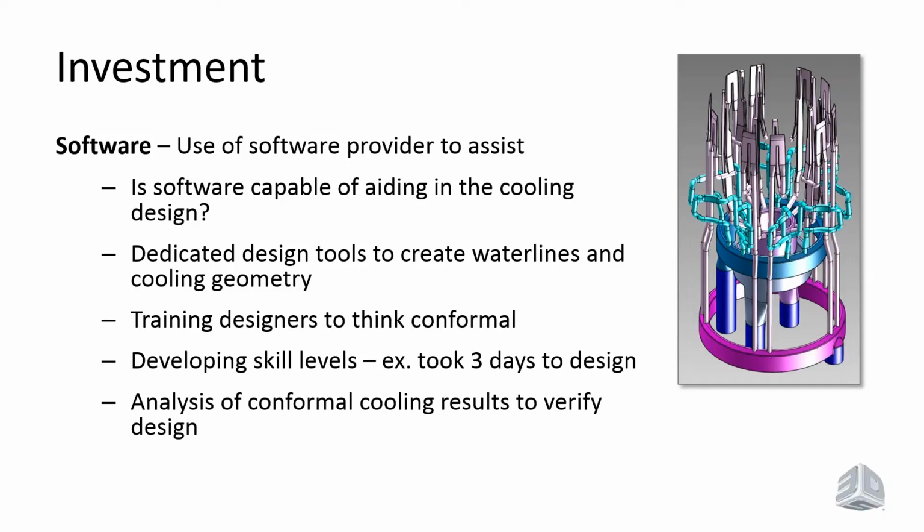That's taking the water line through an analysis software like Moldex, checking to make sure that the water line is going to take the heat out, there are no hot spots. If there's something that doesn't look right, it's going back, tweaking it, adjusting it, going back through the analysis again. So it's more of a process of 3 days rather than just sitting there actually building geometry for 3 days. And that's why that analysis tool is so important, so that we can double check the water line, make sure we're getting the most bang for our buck when it comes to the design time and effort that we're putting into making a good conformal cooling water line.